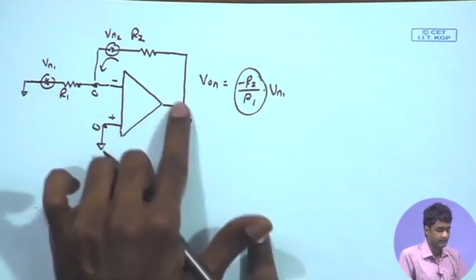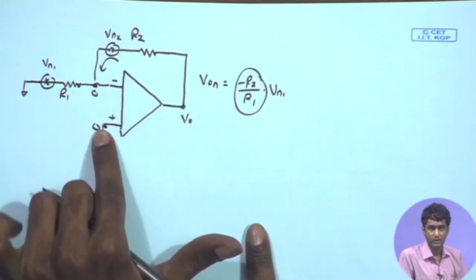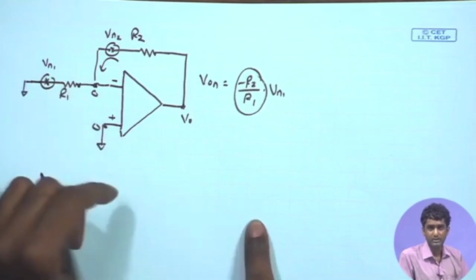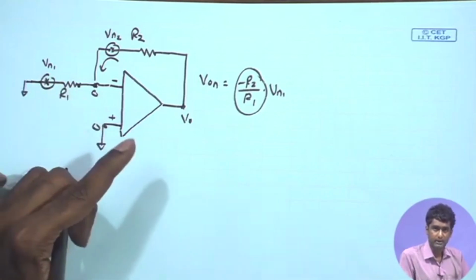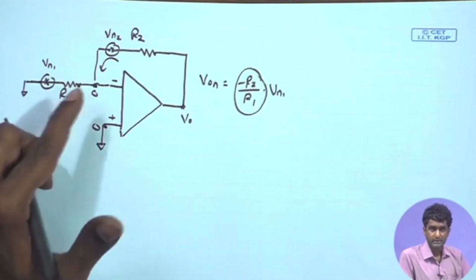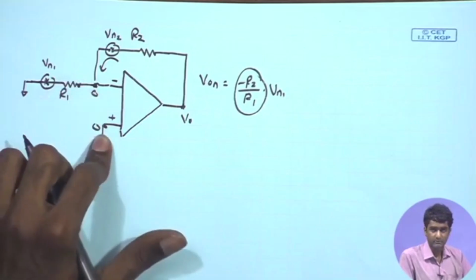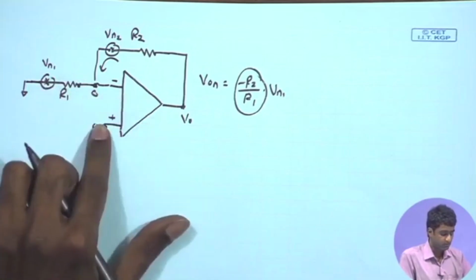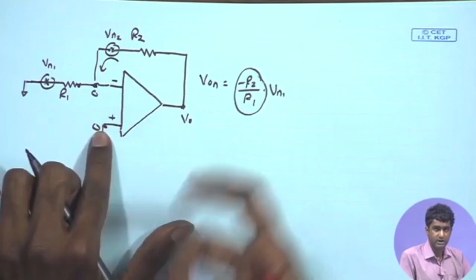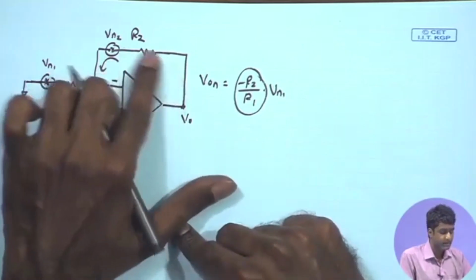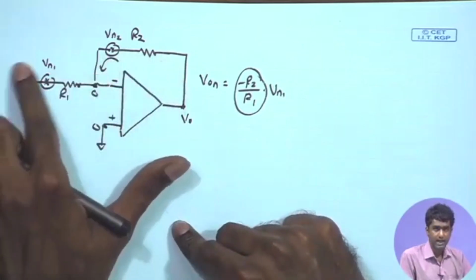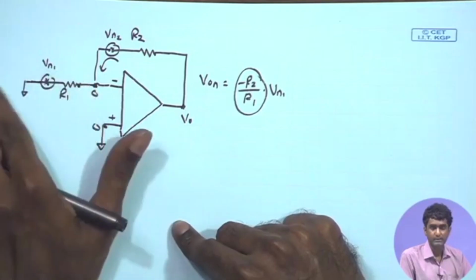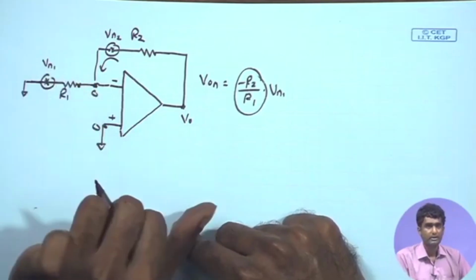So, if the feedback signal is coming at the complementary node as compared to the applied input signal, then it is a series feedback. The input quantity is subtracting from the feedback quantity, because the feedback signal is fed to the complementary terminal. But here we see that the feedback signal is fed to the same terminal as the input signal, therefore, the input quantity has to be treated as current.